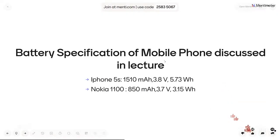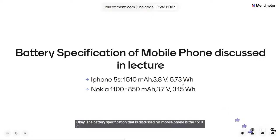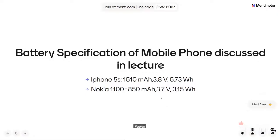The battery specification discussed for the mobile phone is a 1510 mAh battery with voltage and power, which we already discussed when talking about the battery. So there are three important ratings: voltage, current in milliampere hour, and power. If you multiply 1510 by 3.8, you get 5730 milliwatt hour, which in watt hour is 5.73.